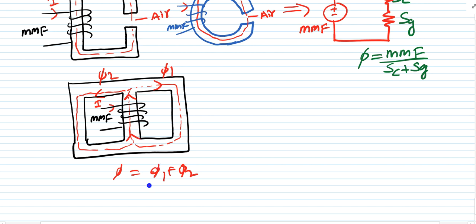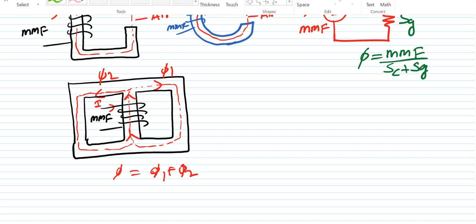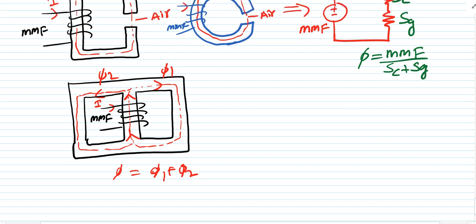So this is the parallel magnetic circuit. If you look here, phi 1 plus phi 2 is coming. So what are the possible cores you can see here? My flux is dividing here, therefore it looks like a parallel network.